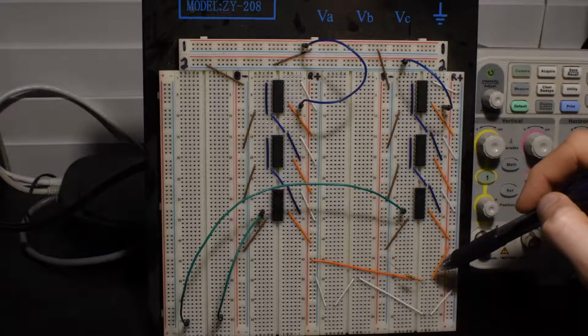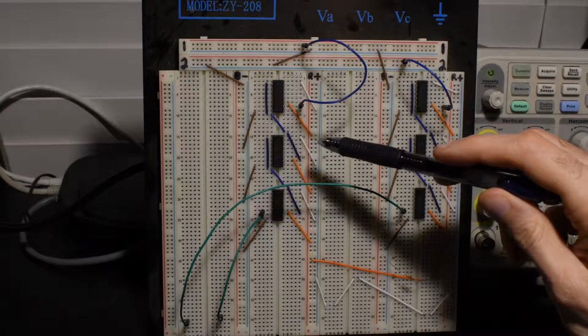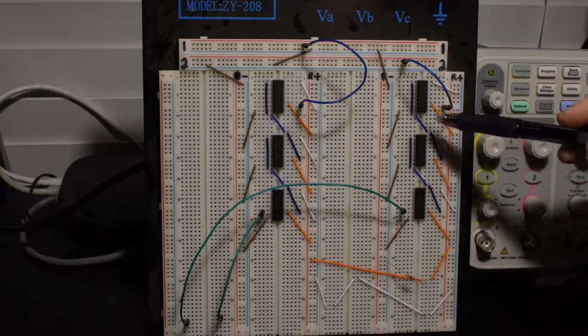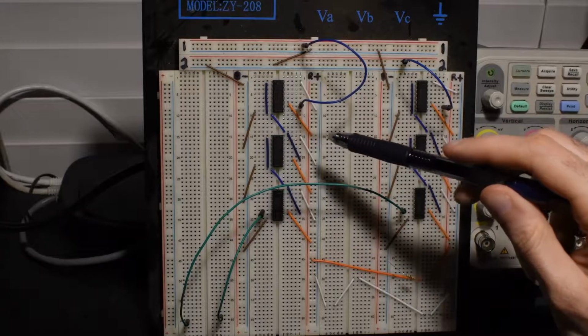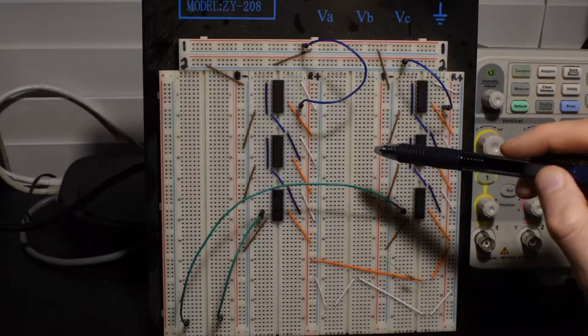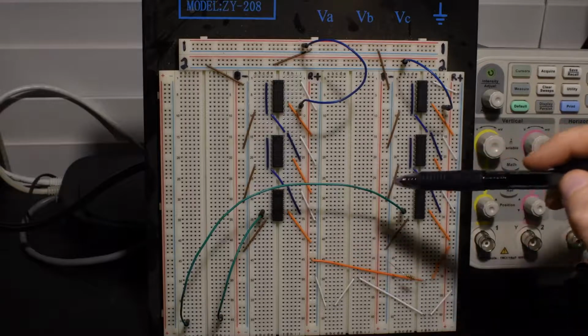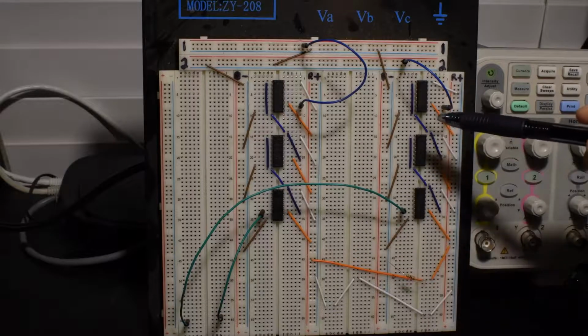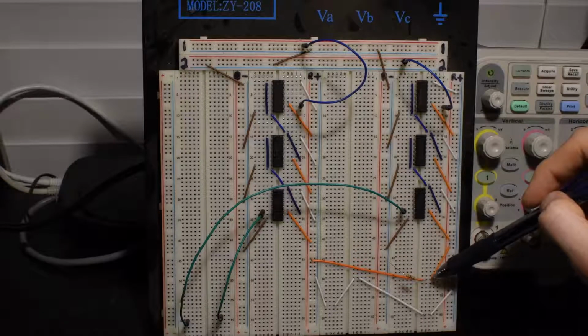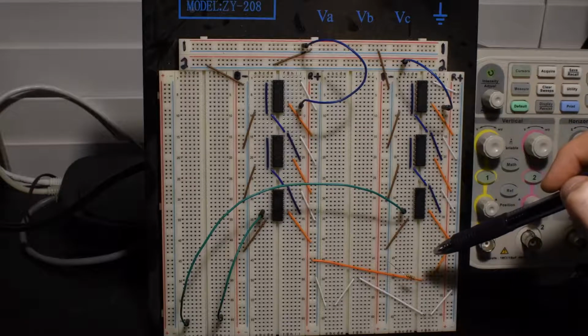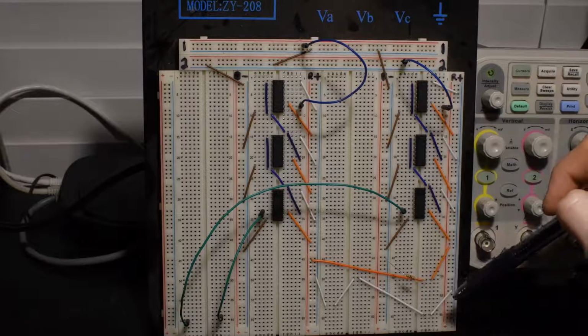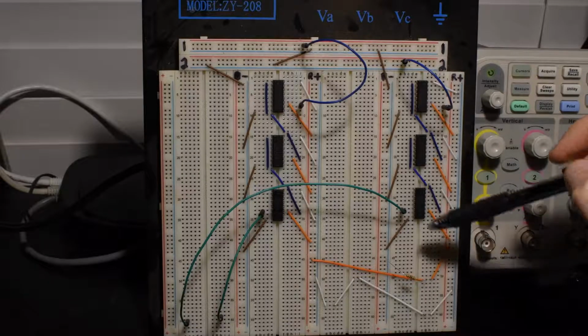The reset on the left chain and the right chain are connected together, and so the entire reset bus connects to all the pins on all the counters, and they meet here where there's a 50 ohm resistor that connects the reset to ground. So this is reset by a high voltage on the reset lines.